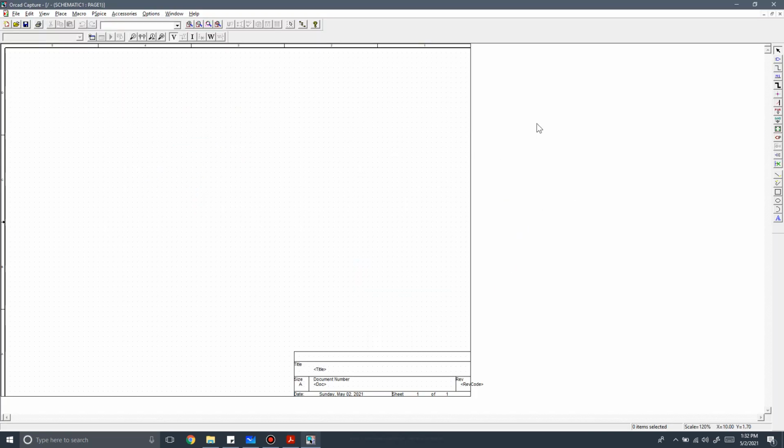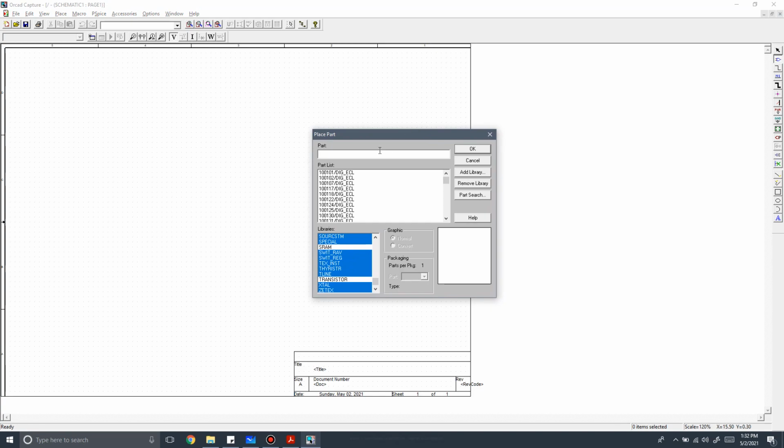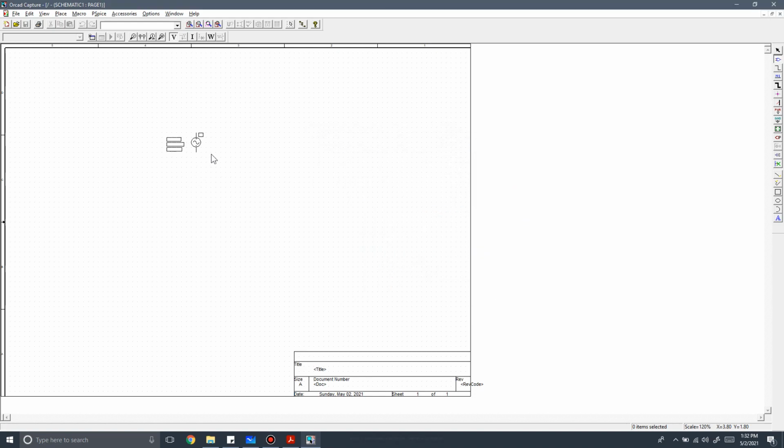First of all, let's click on place parts, and you will get this window. The first thing we need is our sinusoidal voltage source. To find that, we write VSIN. Then select the option that says VSIN/source. There could be multiple sine wave sources, but we want the one that says VSIN/source. Press OK, and you will get the device as a draggable icon. If you click anywhere on the board, you can place your component. That should be very simple to do.